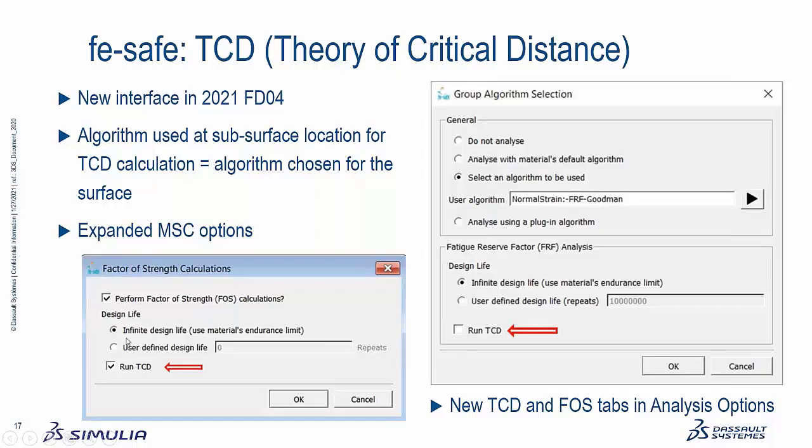If you look at the critical distance, the material property, it does actually vary with life, the number of cycles that the structure is going to experience. If you just go with the infinite life critical distance, you're going to be conservative. You may actually be too conservative because that distance actually increases typically quite substantially as you move towards a sort of lower cycle regime.